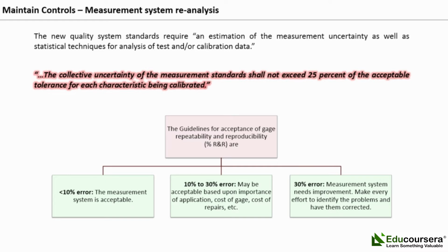Each organization needs to determine the measurement system requirements and evaluate if the measurement system capability meets those requirements. The requirements are dependent upon customer specifications, the intended use, and costs of implementation. As the process capability improves, the measurement system needs to be re-evaluated to determine if requirements or measurement capability also needs to be improved to achieve the desired levels of control.